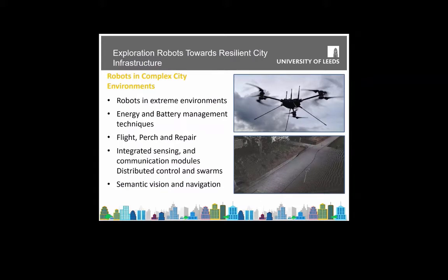Sorry, yeah, okay. But in terms of the real world, of course, robots have to interact with really complex environments. You also have things that are perhaps not very obvious, like energy and battery management. As battery power fails, performance can change. So if you're trying to verify a system working in a particular environment, it may not behave the same way, even within its standard operating procedures. It may be that as the battery gets halfway through, the power starts to change, and so forth. So things can actually be doing that.